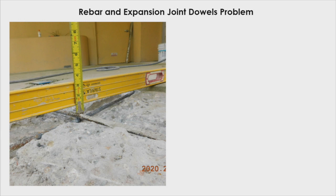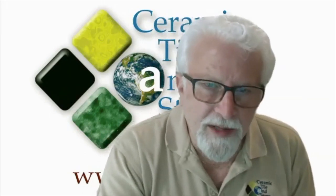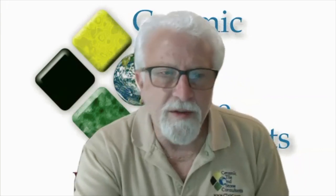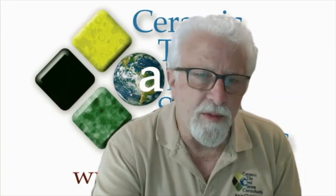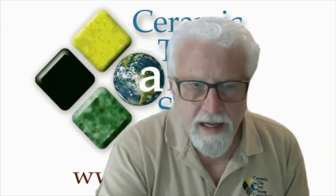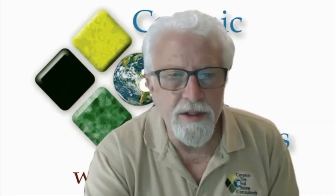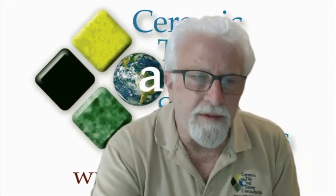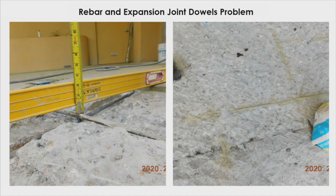So we had to grind below the rebar and bend some of it down to get it to a depth so that once our mortar bed and everything's over it, we have at least 1 inch covering it, because that's what's required according to ACI standards. In order to keep it from corroding, you need to have at least 1 inch thick of mortar or concrete over the top of it.